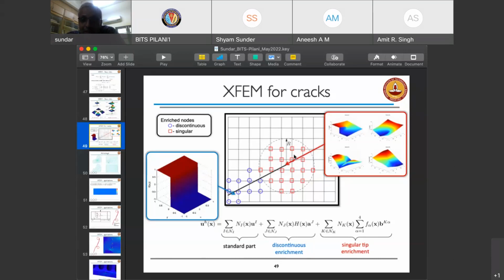So the first fundamental frequency should not be 0. There has to be some problem with the analysis. But she said, this is what I get. And remember, if somebody goes ahead with the design and manufactures it, that would be a fatal accident. When we probed into it, it turned out that the engineer who did the stress analysis forgot to arrest or couple one of the components with the rest of the components.